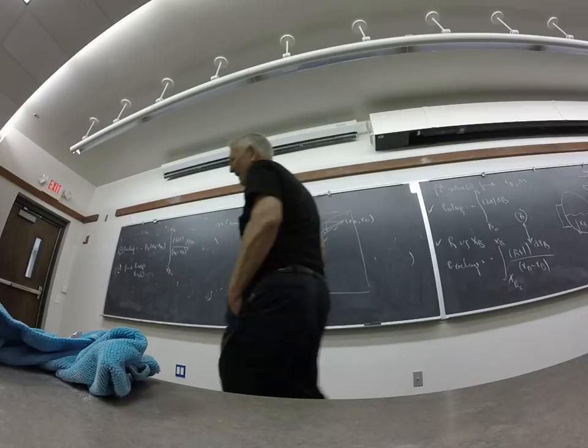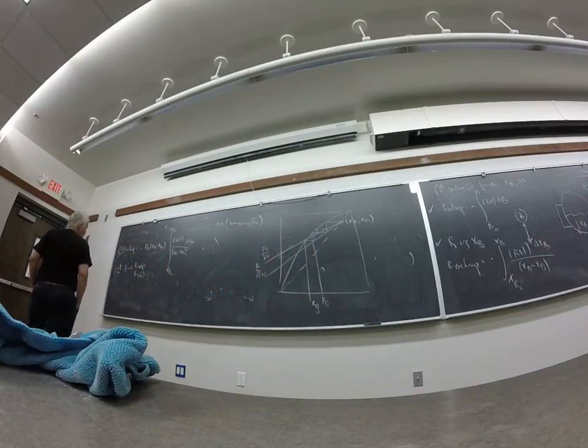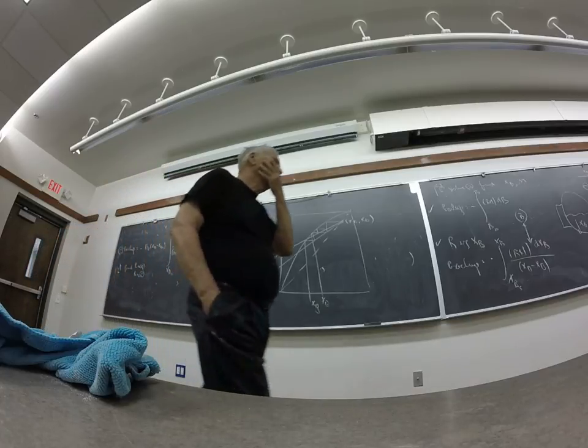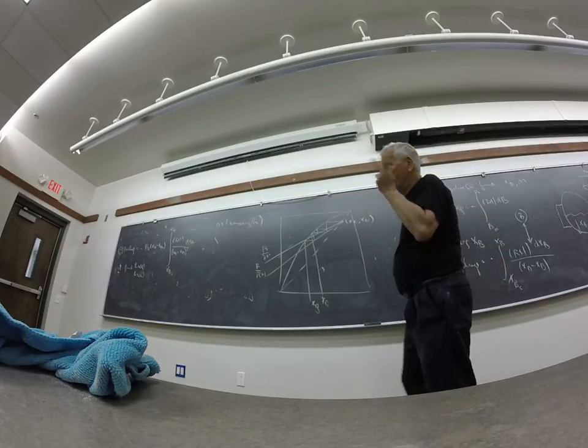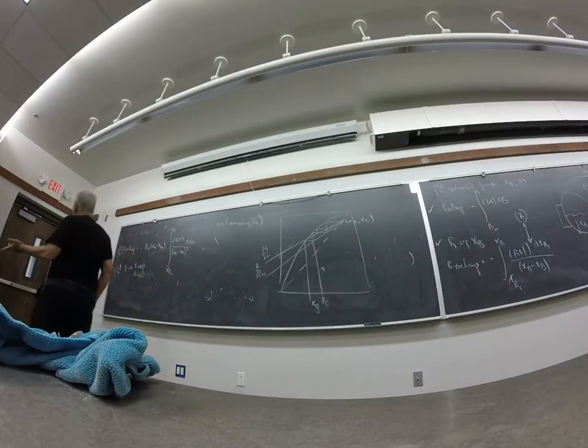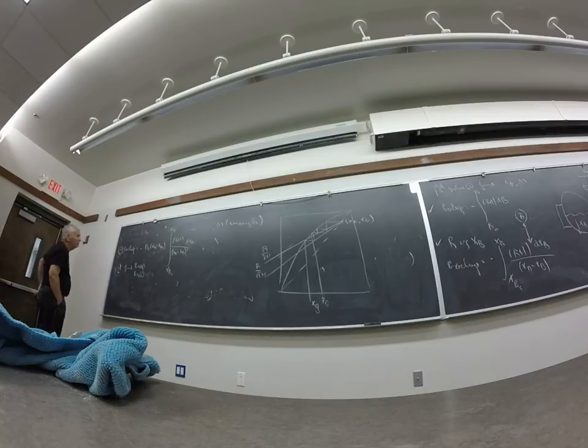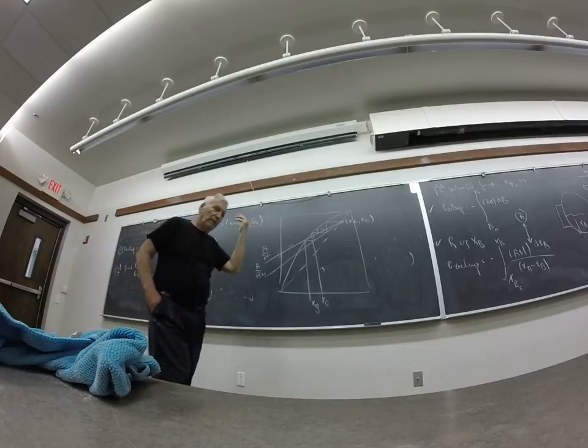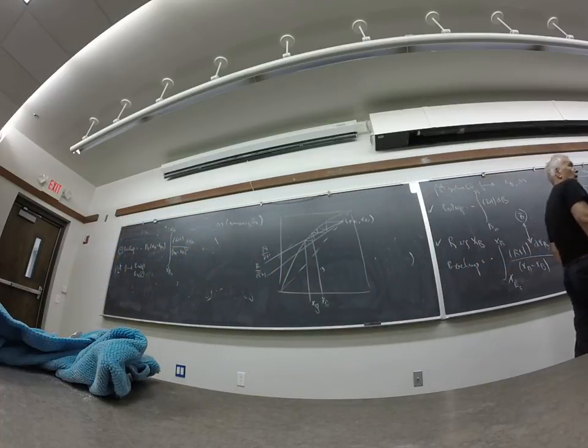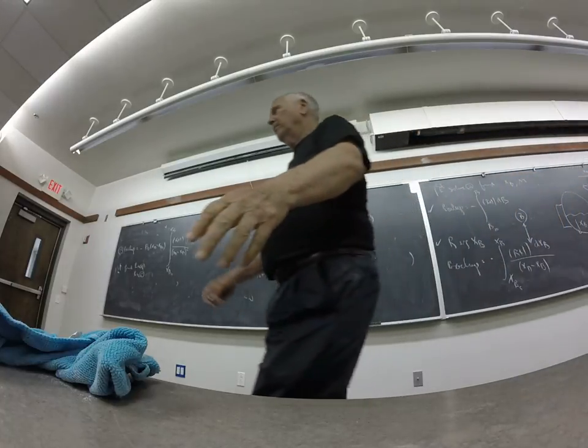However, sometimes the calculation gets a little touchy, because even though you might be able to make the product specifications at a given r, you might not be able to make them when you're increasing r. So the best thing to do probably, and of course if you can't make it in case 2, then case 2 loses automatically. So maybe the easiest thing to do is to set the boil-up in 2 equal to the boil-up in 1, calculate xp, calculate the recovery, and make the choice on the basis of recoveries. Choose the one with the greatest recovery. So that's how that problem goes.